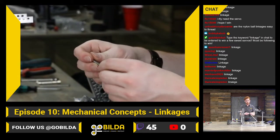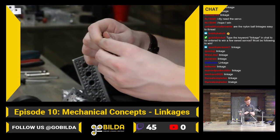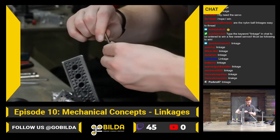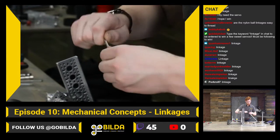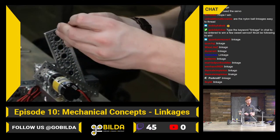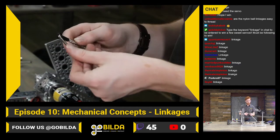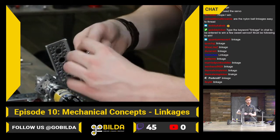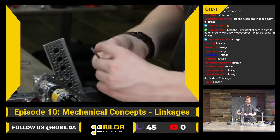The nylon, you do cut your own threads, so you want to make sure you line it up correctly, and then give it a little bit of force to start out that thread. And then once you're in there, they do thread on fairly easy. My favorite thing is to grab a piece of threaded rod, just like this, and use it kind of as a T-handle, so you can stick it through that linkage and rotate it pretty easily.